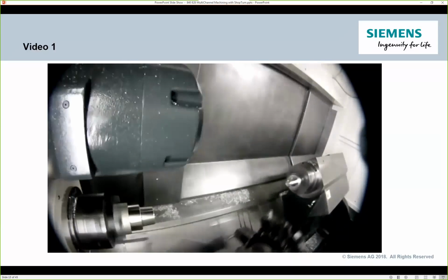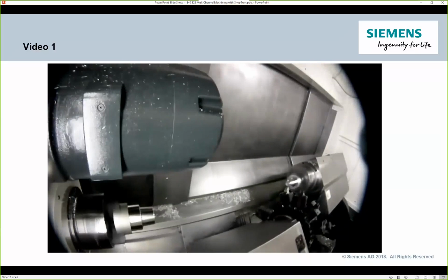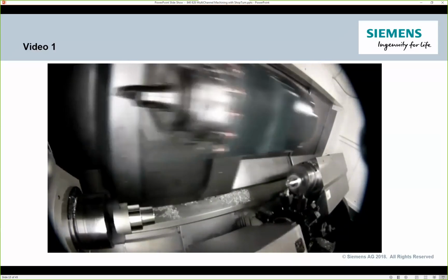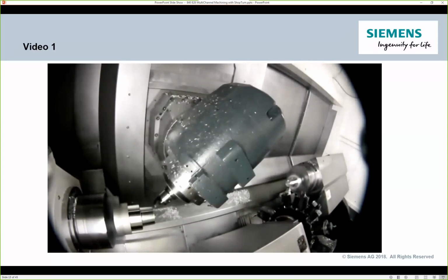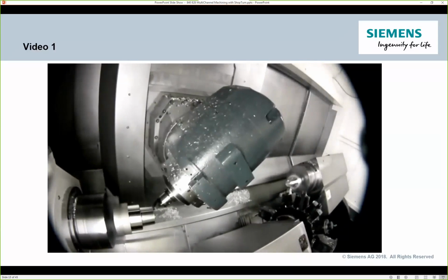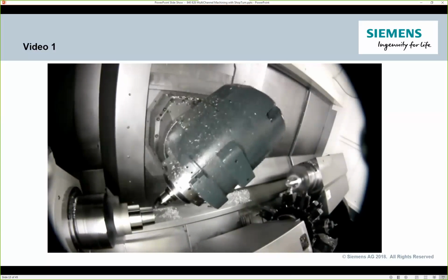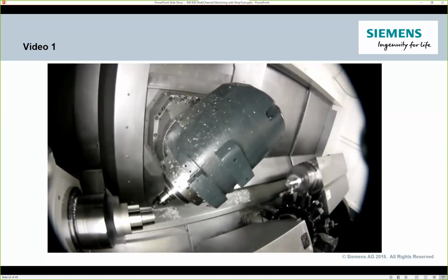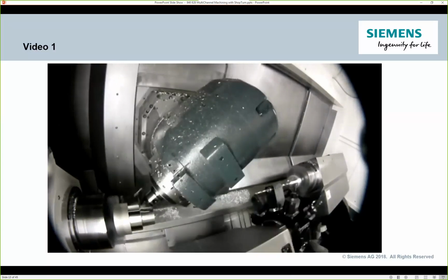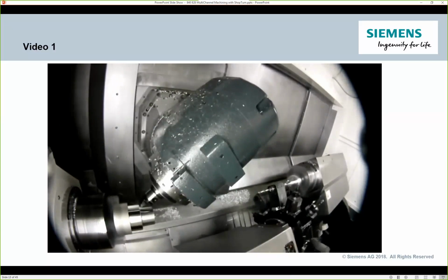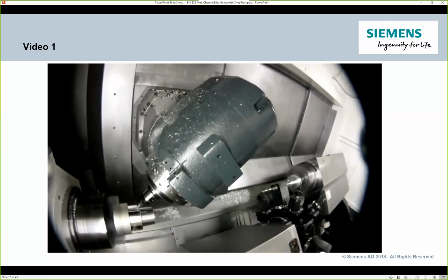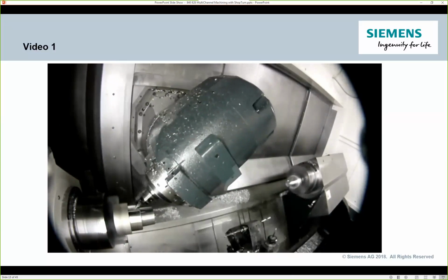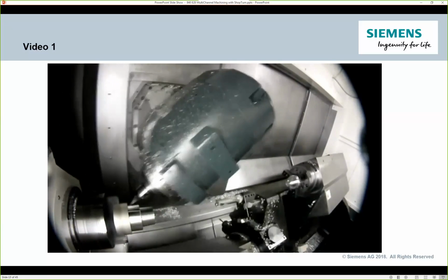And that allows me to start doing work on either of those two spindles, the main spindle or the counter spindle. And then I see more of a traditional turret working on the bottom of the screen or towards the sub-spindle or counter spindle area. Now, what's neat about these channels is they're completely independent of each other, but they can be timed together. So I could have the two channels working on separate operations like I see here, and obviously just streamlining processes.